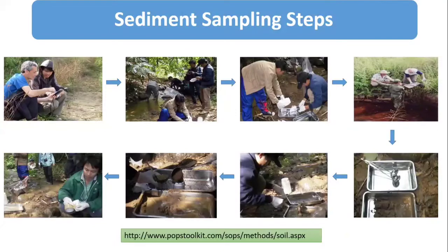Repeat the collection until you get your desired volume or quantity of sample. Then make a note of how many times you have done your grabbing. Then, using the stainless steel spoon, mix the sediment sample until it is thoroughly combined into a single homogeneous sample in a mixing tray. Then transfer representative subsamples of the homogeneous mixture to the clean sample jar using the mixing spoon.